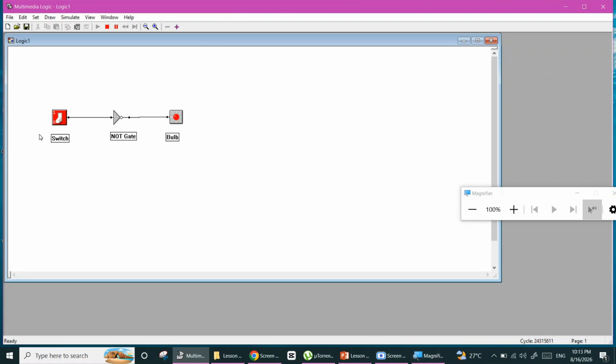It means this is the false value 0. If we input a false value through a NOT gate, then our output is a true value. It always takes the opposite of the input. Here our input is a false value, then the output is true. If our input is a true value, our output is false. So this is the circuit we developed to identify the function of the NOT gate.